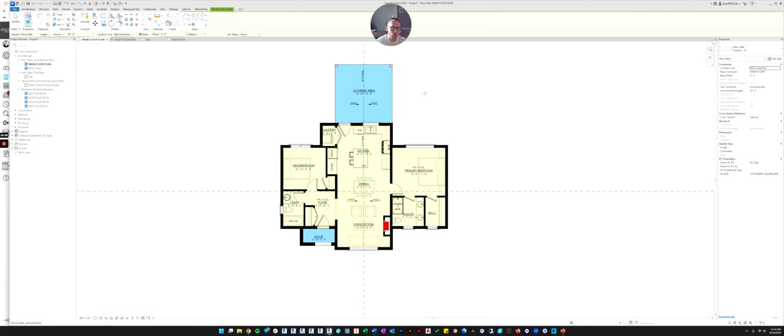While we're in the wall command, if you go over to the properties, it tells you the properties of the wall that you're about to create. So this is a good time to understand a little bit more of the properties. We talked about the base constraint and the top constraint. We also talked about the base offset and the top offset if you picked a top constraint. Otherwise, you get the unconnected height.